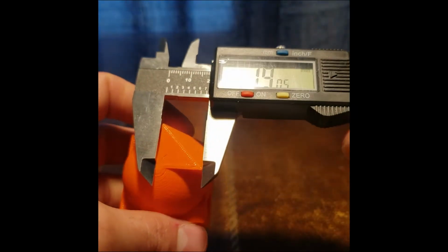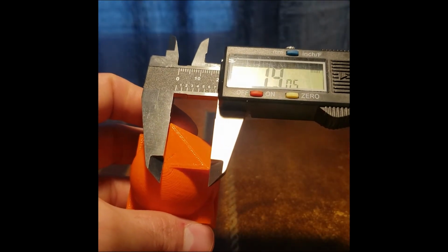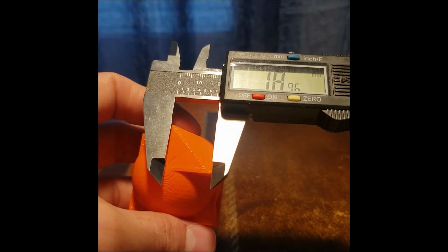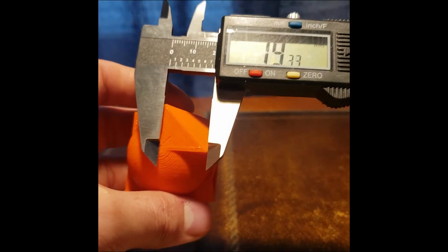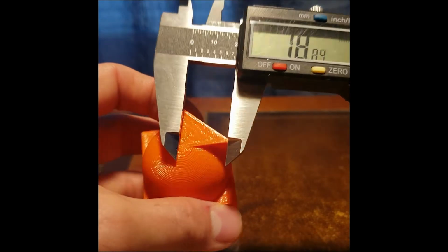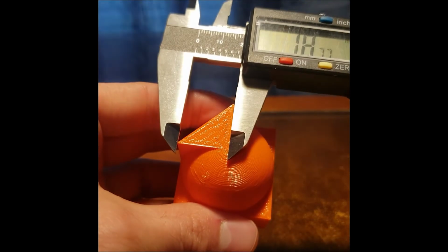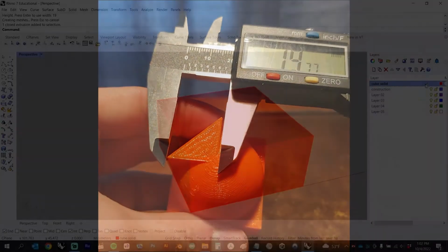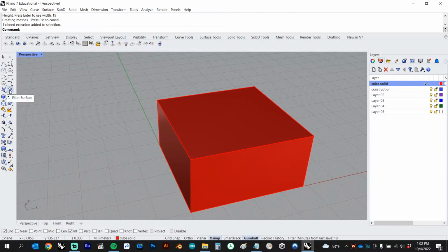To create the geometry that's on top of the platform, we can break these shapes down into a sphere and a box that's been sliced. I need to get some more measurements, but I already know that the height of this box is going to be the distance between the platform and the overall height. Once again, I'm going to use the box tool. I'm going to be sure to use my O-snaps to snap to the top of the platform, and I'm going to enter my dimensions that I measured in the command line.